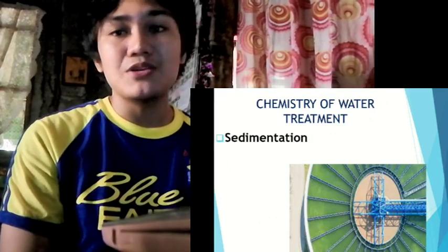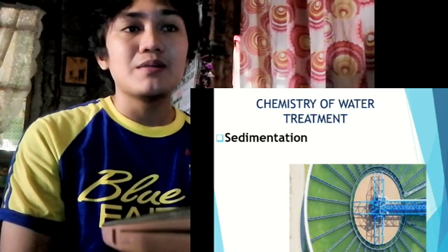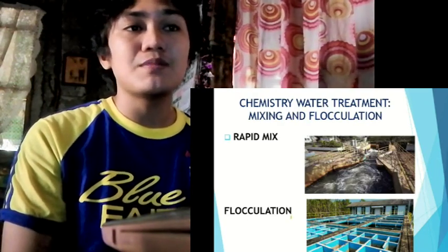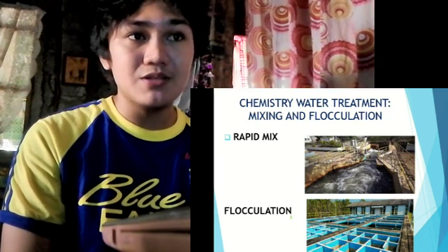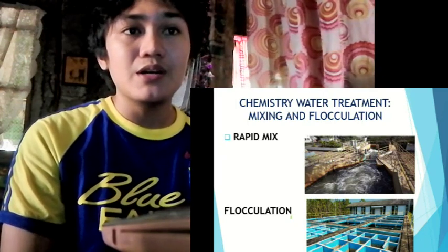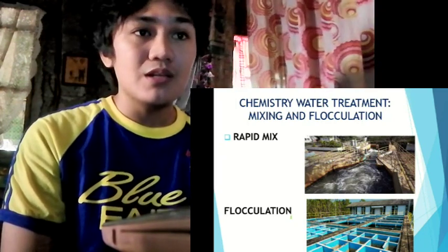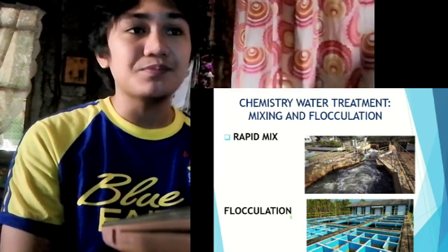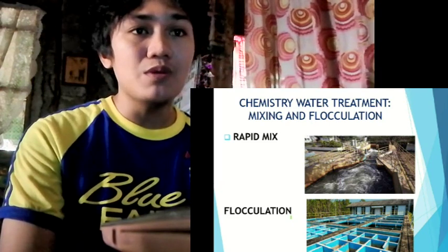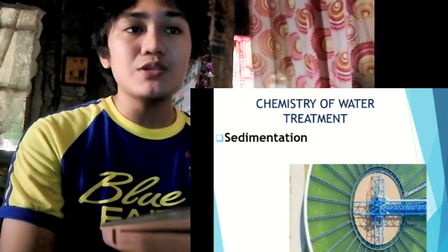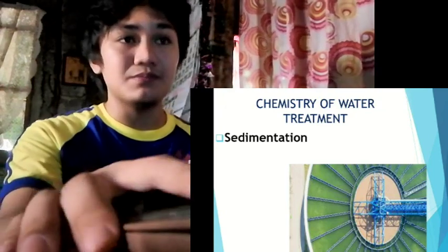Type 2 sedimentation is characterized by particles that flocculate during sedimentation. Because they flocculate, their size is constantly changing. Therefore, the settling velocity is changing. Generally, the settling velocity is increasing. These types of particles occur in aluminum or iron coagulation and primary sedimentation, and in settling tanks in trickling filtration.